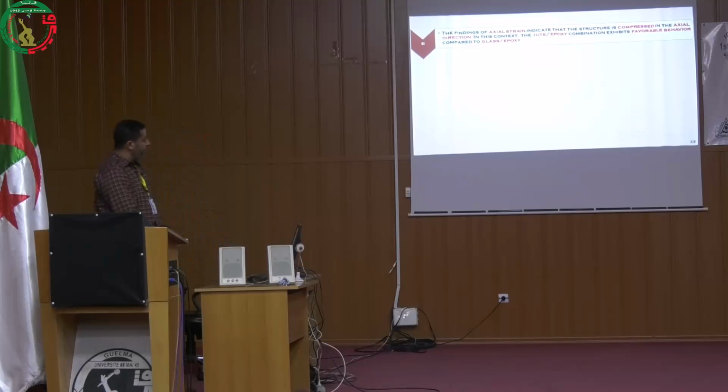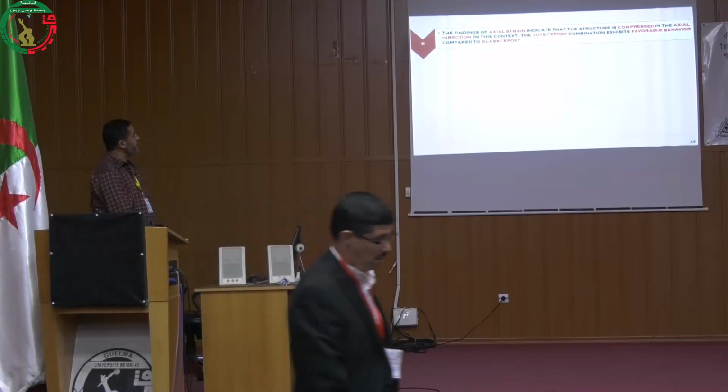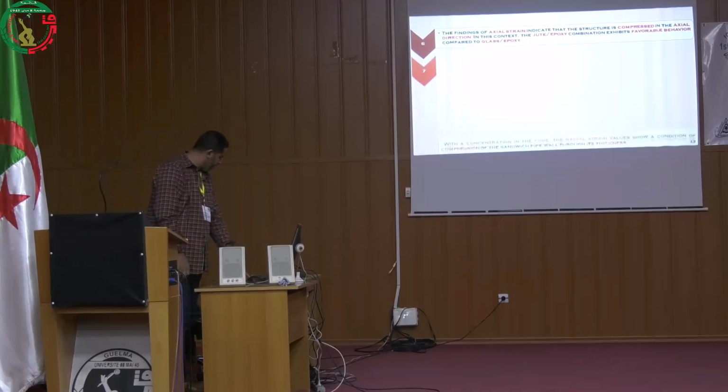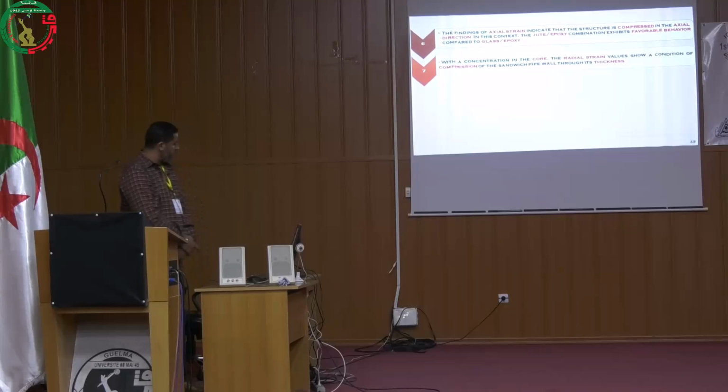The findings of axial strain indicate that the structure is compressed in the axial direction. In this context, the jute epoxy combination exhibits favorable behavior compared to the glass epoxy case. And with a concentration in the core, the radial strain values show a condition of compression of the sandwich pipe wall through its thickness.